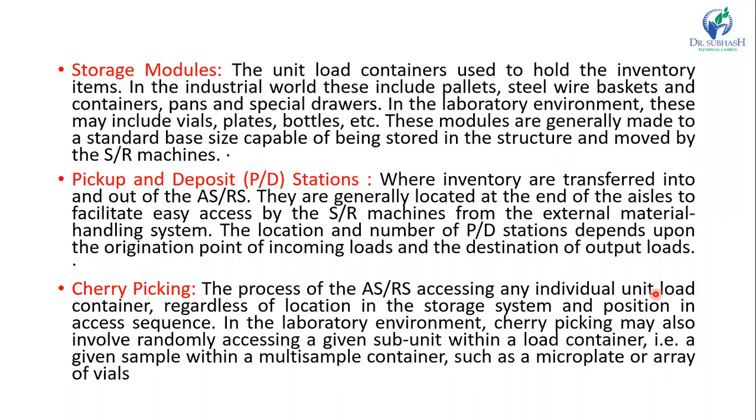Then storage module, the unit load containers used to hold the inventory items. In the industrial world, these include pallets, steel wire baskets and containers, pans, and special drawers. In the laboratory environment, this may include vials, plates, bottles, etc. These modules are generally made to a standard base size capable of being stored in the structure and moved by the SR machine, the storage and retrieval machine.